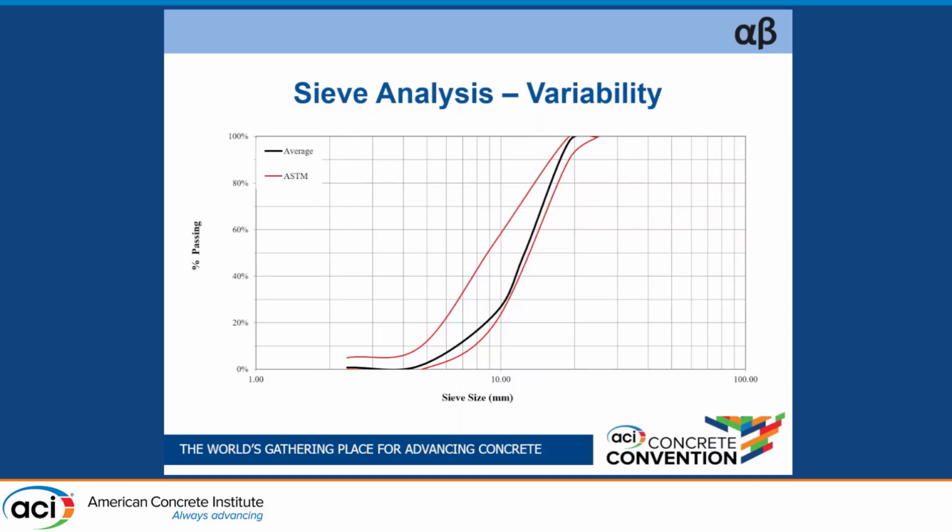So there would be no concern if you average all of this, if you were to sieve all of your samples as opposed to just the single 5 kg units. But most people don't do that due to time constraints or whatever else. But we find that by using a tool like digital aggregate, you could image all of that aggregate and get a true representation as opposed to just a segmented 5 kg sample.